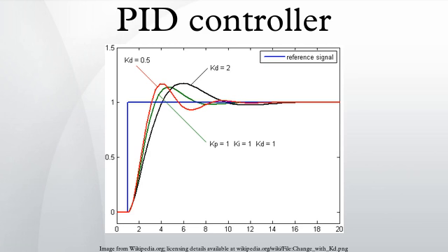PID controllers, when used alone, can give poor performance when the PID loop gains must be reduced so that the control system does not overshoot, oscillate or hunt about the control set point value. They also have difficulties in the presence of non-linearities, may trade off regulation versus response time, do not react to changing process behavior, and have lag in responding to large disturbances.